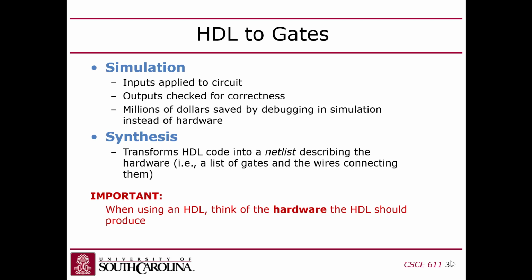Because Moore's law makes computers faster, but Moore's law also makes the designs that you're synthesizing larger at the same rate. So you don't get any benefit. So it takes a long time to synthesize. And then once you synthesize, the problem is visibility. I mentioned logic circuits have those internal signals, right? Once you put your design on a chip, you can't look at the internal signals anymore. You can only see the top level inputs and outputs. So that makes it hard to debug.